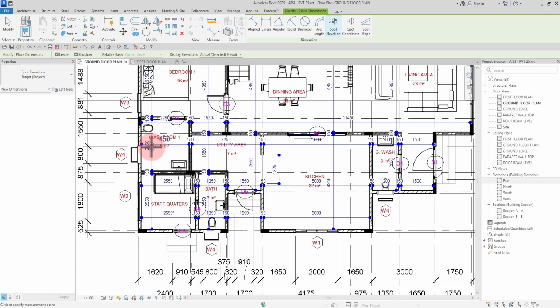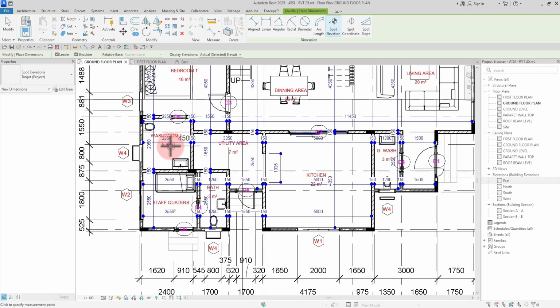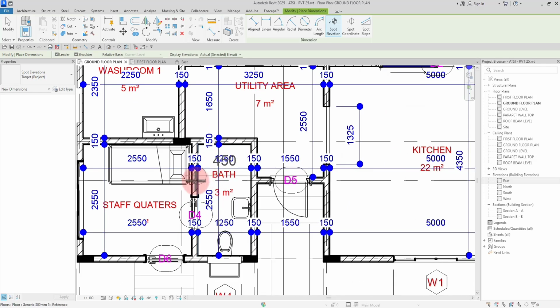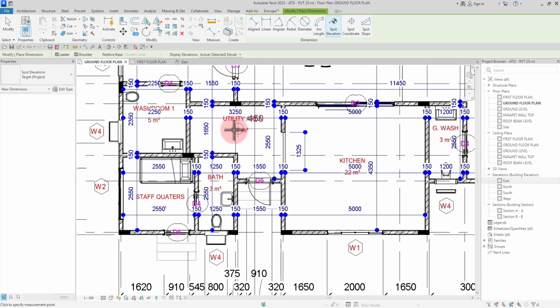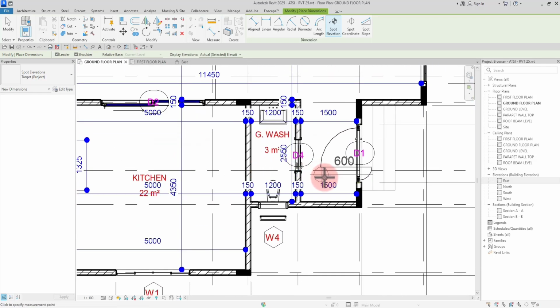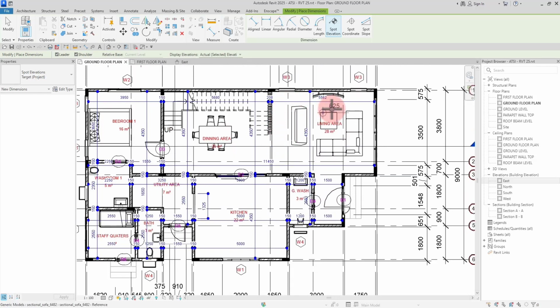Just a step, so that in case water should pour into that space, it doesn't just flow directly into the bedroom. At least it should collect the water in that space for a while before anybody occupying it should notice. So in this staff quarters we have 600, and then inside the bathroom areas I have 450, in here I have 450, in the kitchen I have 450 as well, guest 450, and here you notice I have 600. So it works all through. Here it's all 600, all 600, all 600.